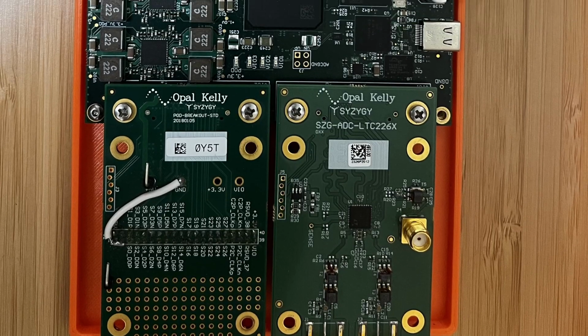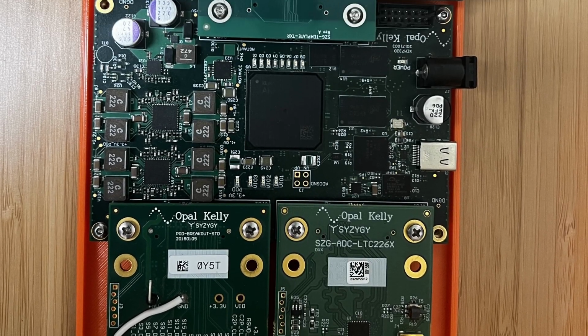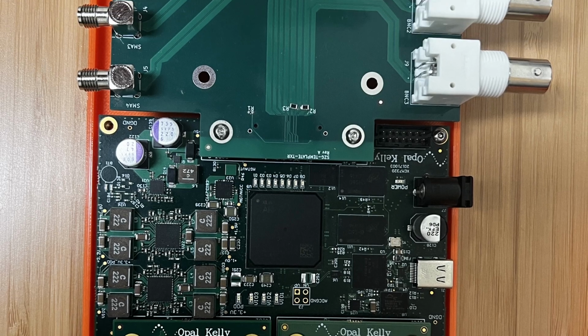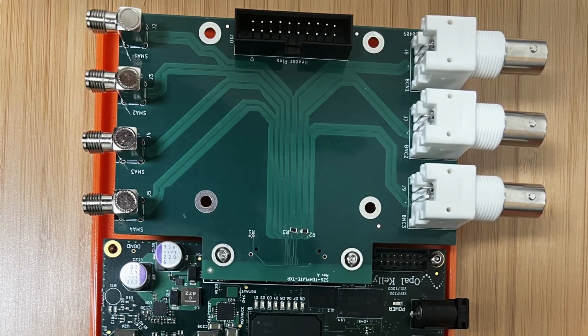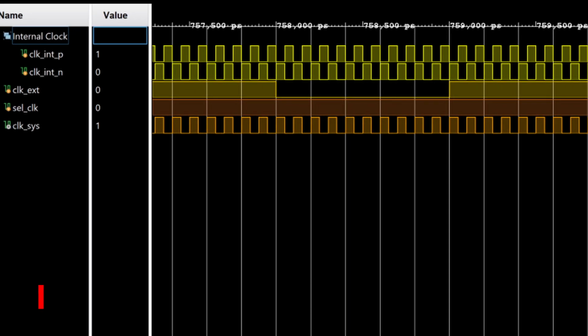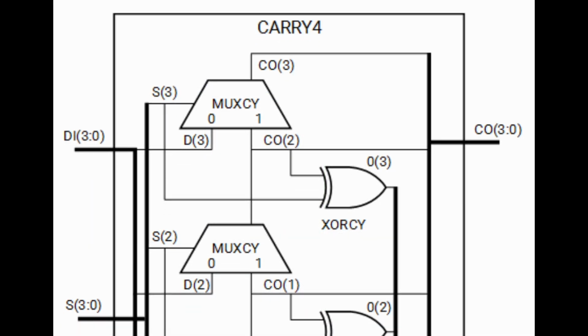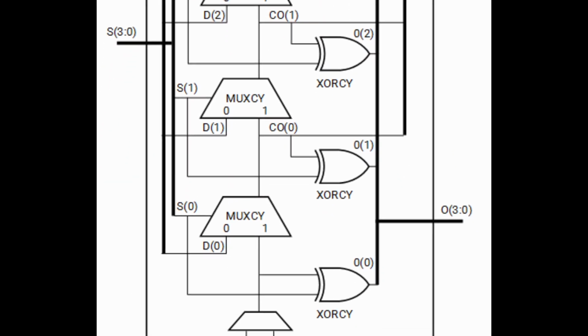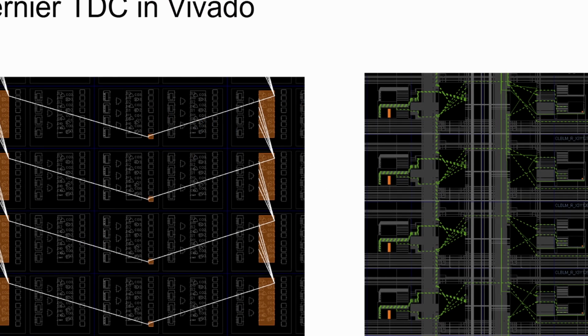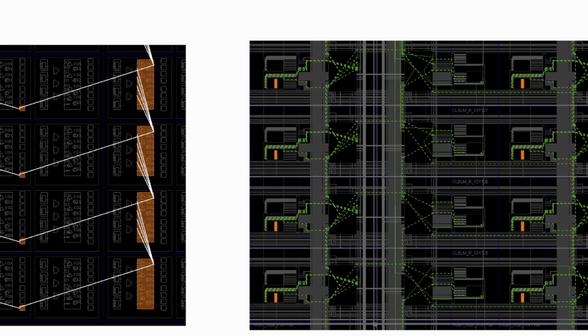Our hardware ensures high signal integrity and supports integration with external clock sources through a custom PCB for improved accuracy and jitter reduction. Getting a reliably externally clocked system to work, not just in simulation, but on a physical FPGA, pushed us to deeply understand physical routing and synchronization. Implementing sub-cycle delays required careful handling of FPGA primitives, adjusting the Vernier delay line, and tuning the time-to-digital converter architecture to meet timing.